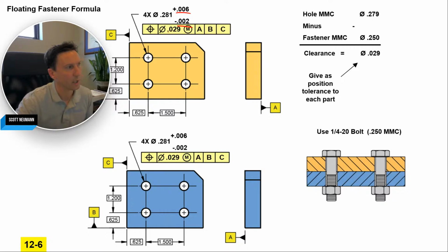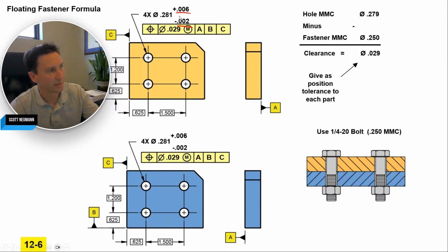Okay, so then you look at drill charts, and they'll recommend a little more plus than minus usually on drilled holes. It's because when a drill becomes dull, it tends to walk and wobble in a hole. So you give the tool more life by giving it more plus than minus. That's what we have, standard drill size and recommended standard drill tolerance there.